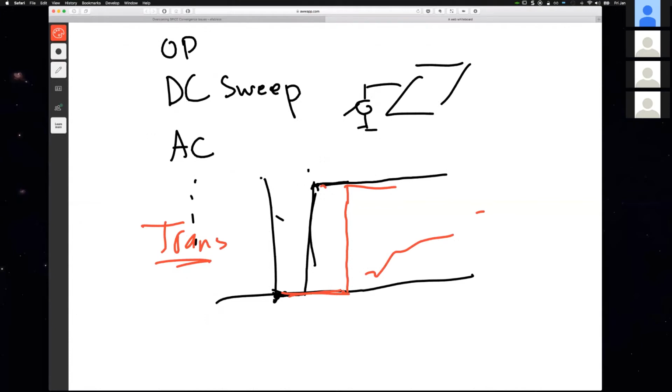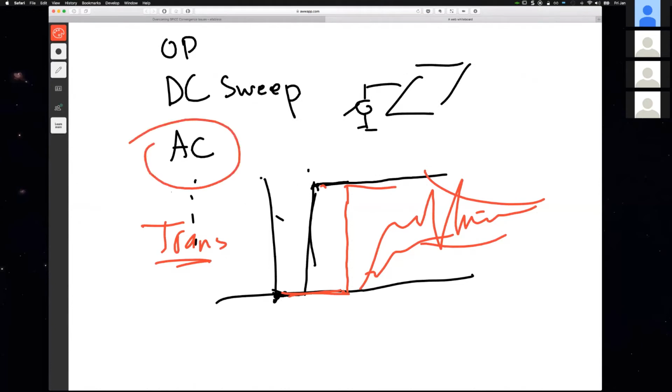So if you have an effect at the output of a reference, and you have some sort of an underdamped oscillation, or it's all about the frequency response of the system, and you're trying to apply either AC analysis or pole zero analysis, or you're doing it by hand, which is preferred for general understanding, you will understand the different views of the transient behavior. So it's always recommended that you try to replicate the transient behavior.